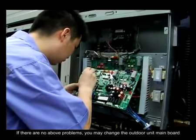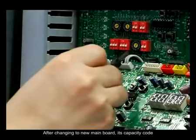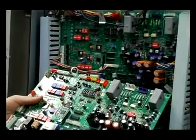If there are no above problems, you may change the outdoor unit main board. After changing to new main board, its capacity code, address code must be the same with before.